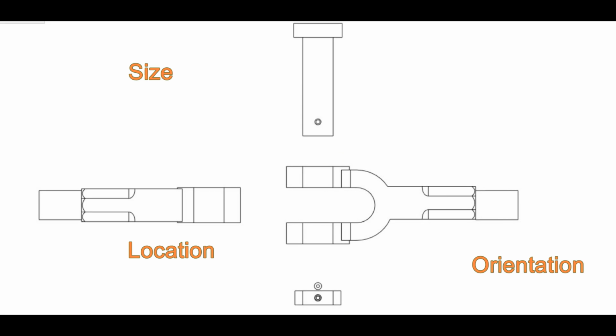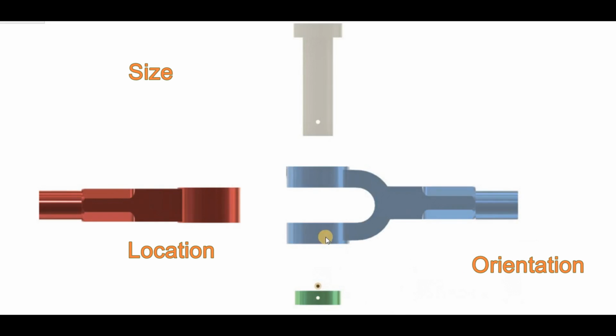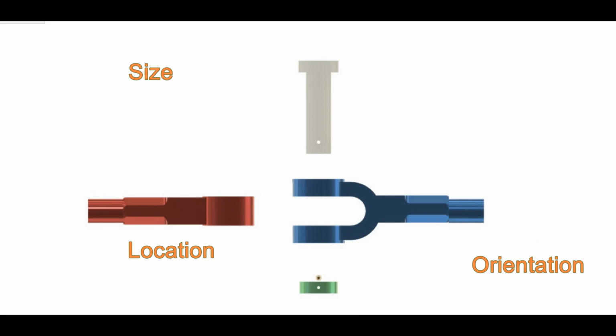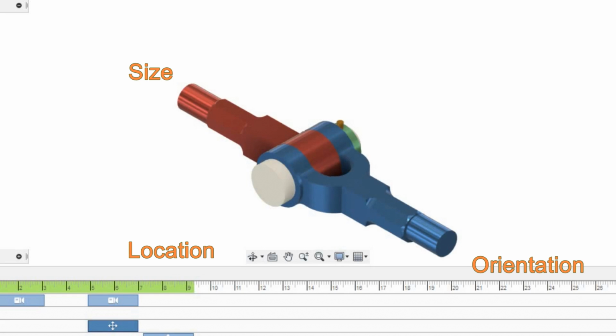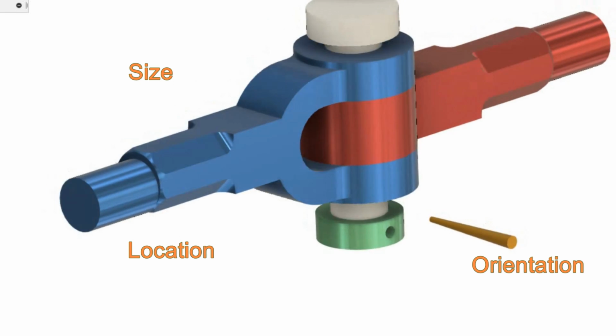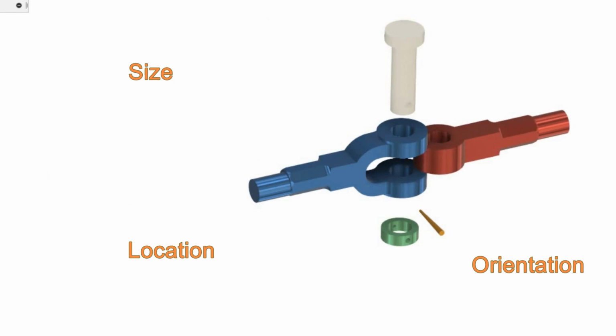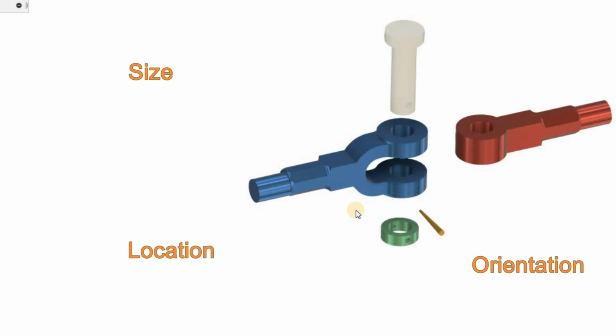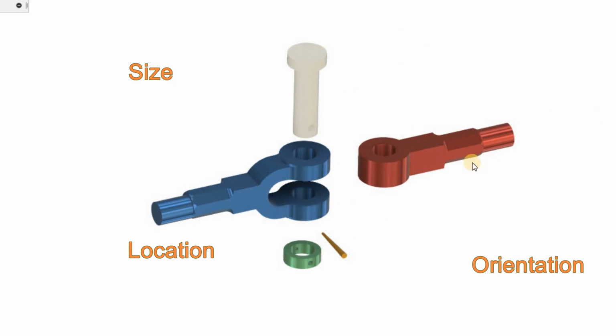Let us first see how this part is going to be assembled. First the stepper pin will come out and then these parts will go out. So this is how it has to be assembled. Here we see that the cylindricity of the pin and the roundness of the hole also affect the assembly. So form tolerances should also be taken into account.